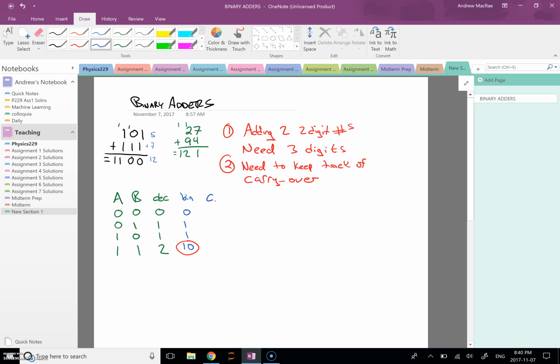We'll have 2 bits of an output when we're adding two 1-bit numbers and the original sum. So here carry is going to be 0 and 0, 0 and 1, 0 and 1. And when we add 1 plus 1, we're going to get 1, 0, 1 carry, and 0 in the sum column. And we can look at these truth tables independently. We can say that this is none other than an exclusive OR. And this is just an AND gate.